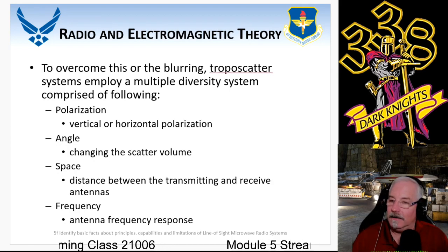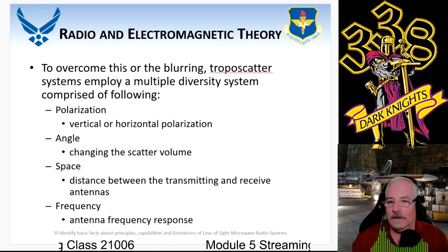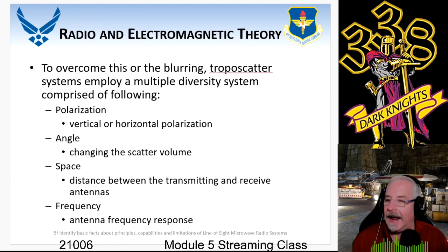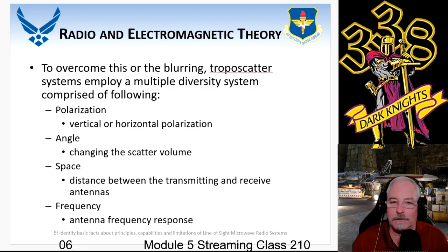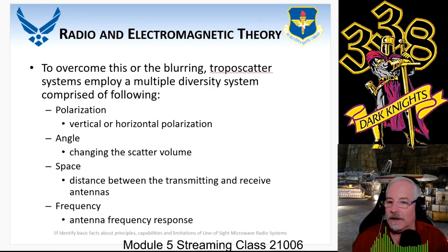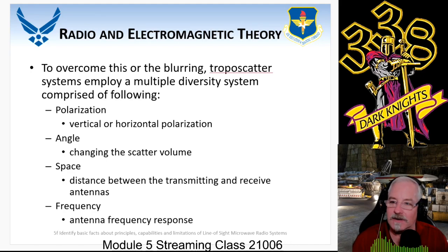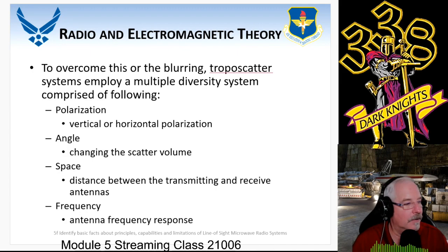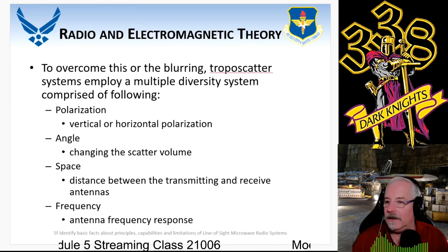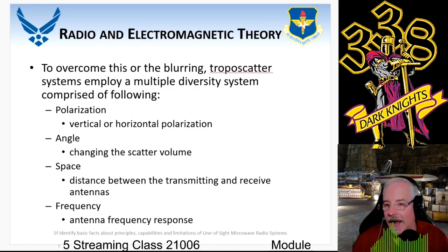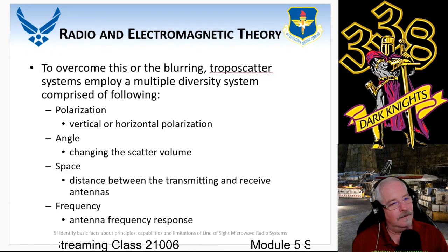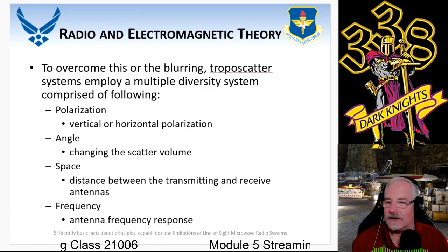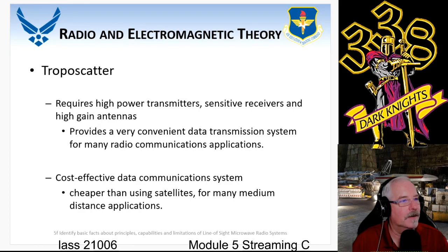So you get something like that, as opposed to if you were, let's say, 20 miles to 100 miles apart. You're not going to have that issue with space, because the transmitting and receive antennas are very sensitive. And that was the reason why we were having problems all the time with them, especially if you did it in the hallway. The hallway acted like a waveguide, and sometimes the receive end on both of them would get saturated and we'd have problems with it.